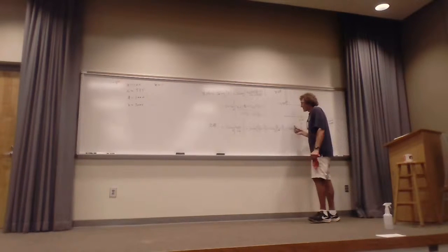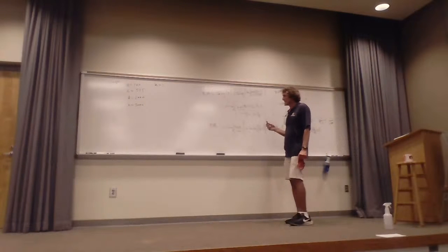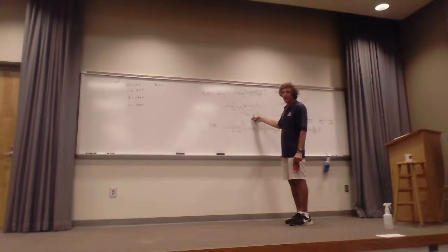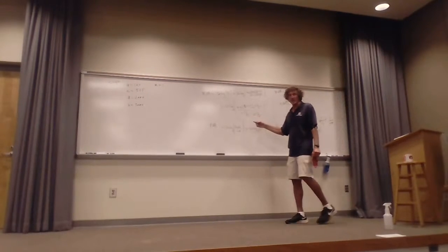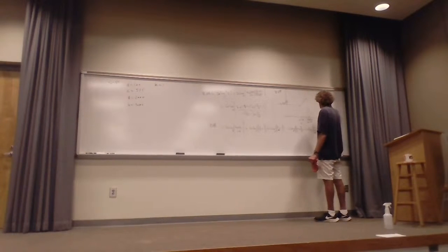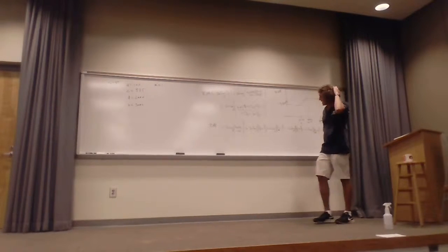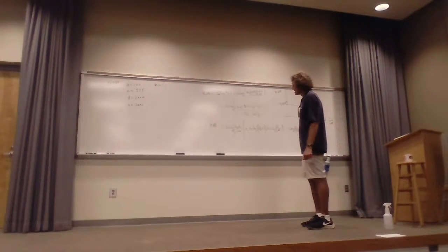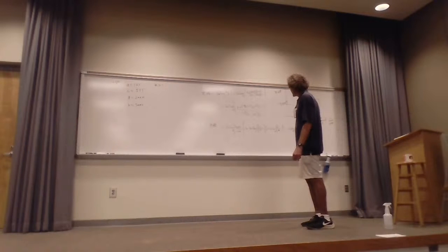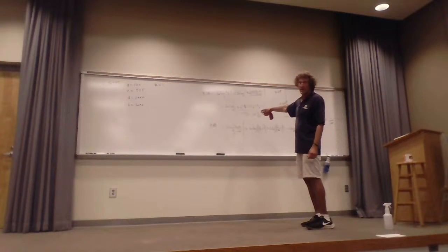So when we hit 525, that's C, and C is a pole, right? So now it's going to start going down by 20 dB, which means it flattens out, does it? Then I hit 2,000, and 2,000 is another pole, right?